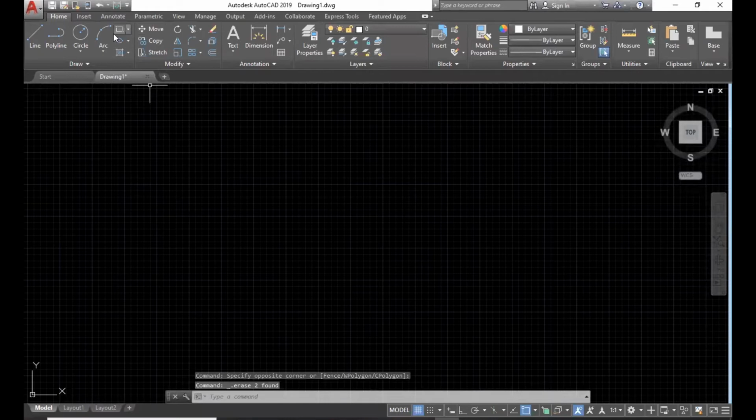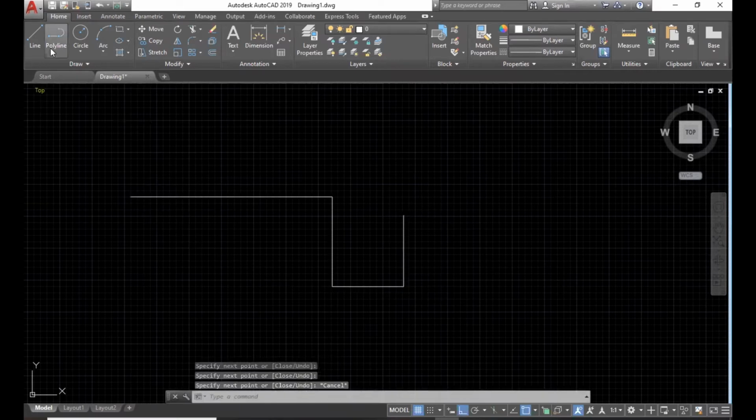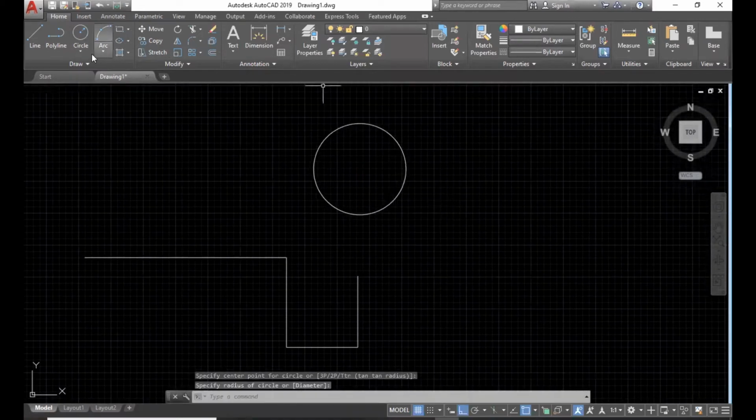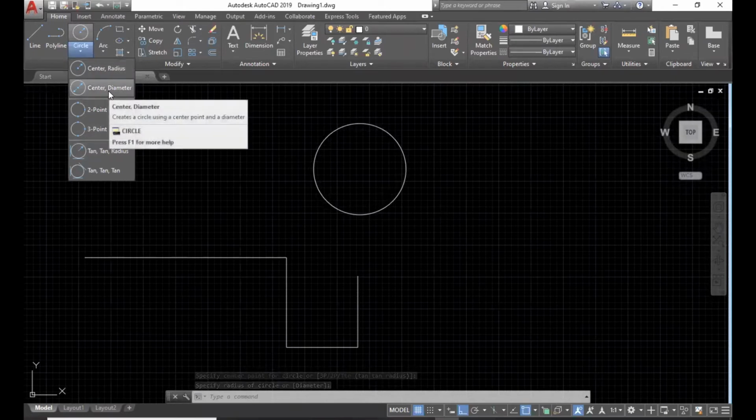Now, we're discussing the tools in the drawing toolbar. Some of the things we already know. About the line tool, we already discussed, right? When we switch on ortho, you can get straight lines, we discussed. We discussed the circle, and different types of radius and diameter. If you want, we'll use diameter.